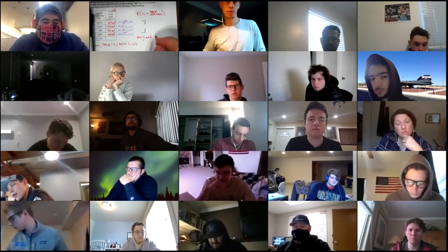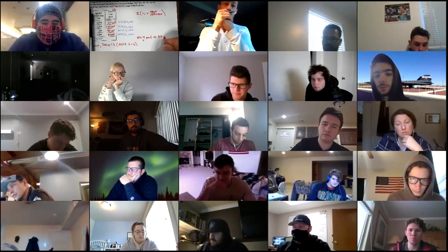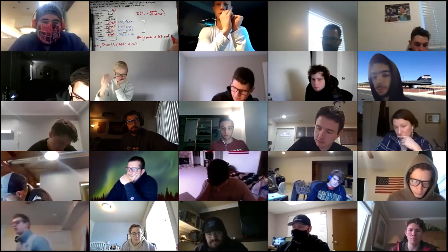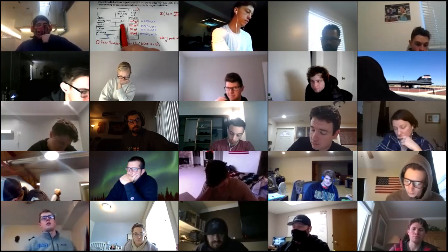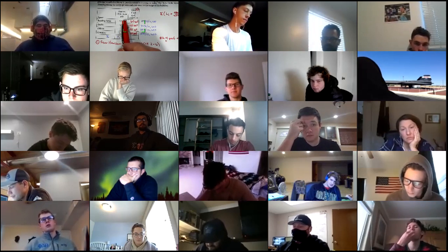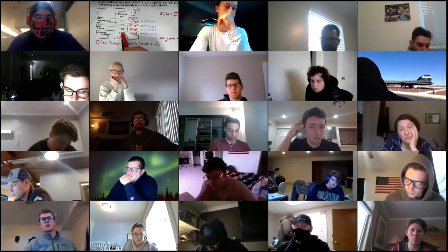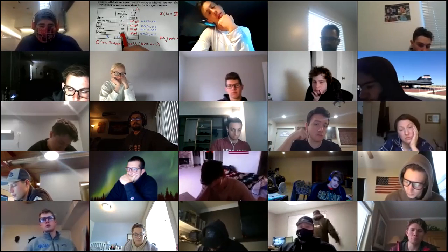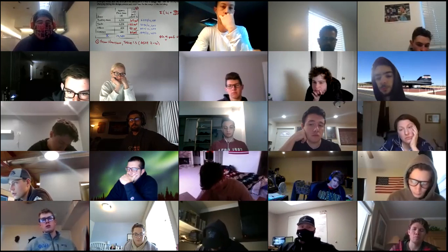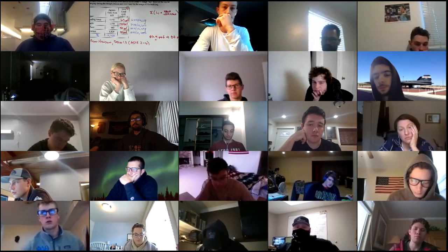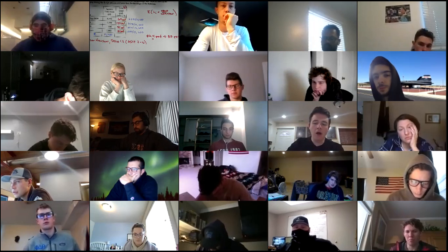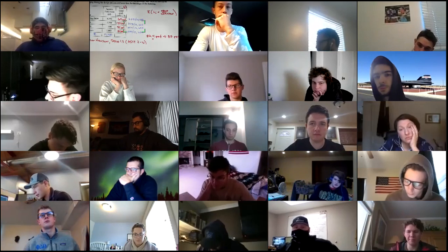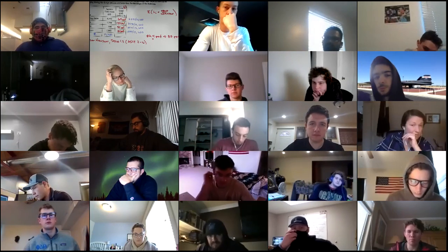So if anything, I would round this up to 87 PSF. Adding 0.6 is not adding anything particularly significant, because I know doggone well that the architect is going to lay out that approximate floor plan to the owner, and the owner's going to say, I don't want to do that. And they'll change something. And if they change it in a minor way, if I design it for 87 PSF, well, I'm golden. I don't have to redo all my work, right? Think about it. You've just done 20 pages worth of handwritten work, and somebody comes along and changes something, and you got to redo all that.